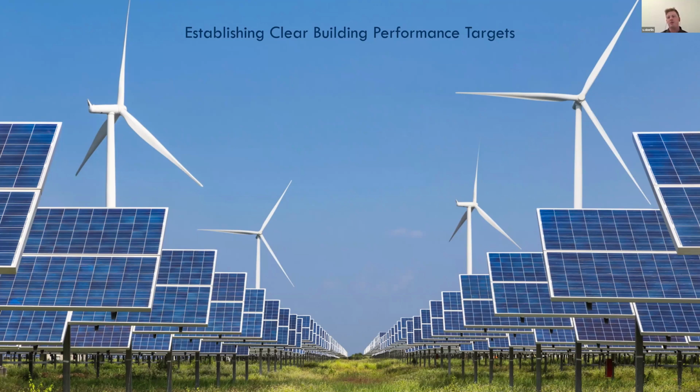So we established the rough geometry of the building, worked on tuning the roof angle and location to the solar orientation, worked with a solar consultant in understanding the net annual availability of solar energy that could be produced, and kind of worked backwards, where we set that as our overall annual building energy performance target, and tuned our building assemblies to be able to hit this target and make sure that we had a bit of a buffer in terms of 2 to 5% of additional net annual production versus our projected net annual usage.